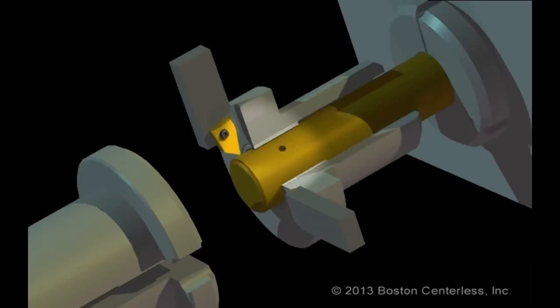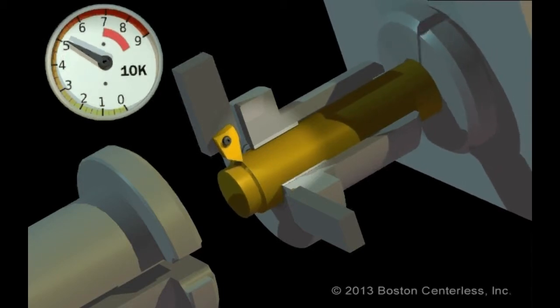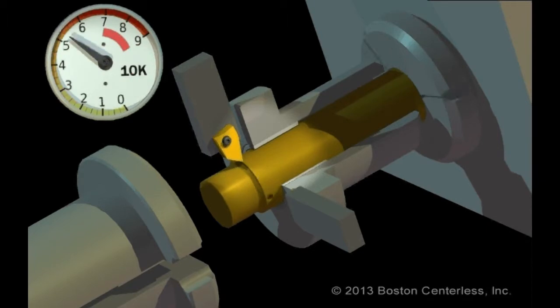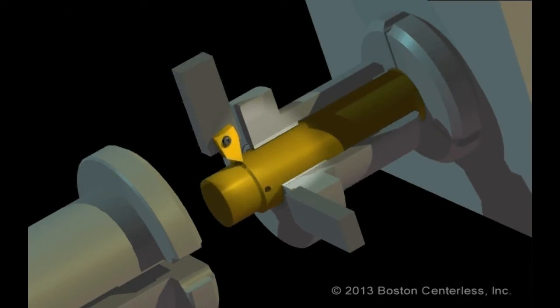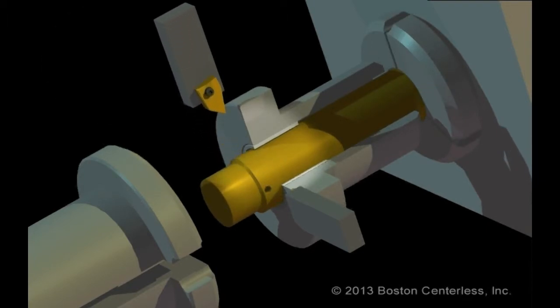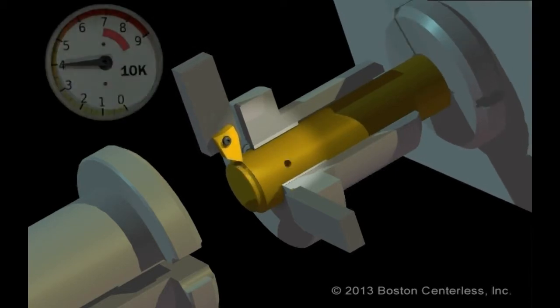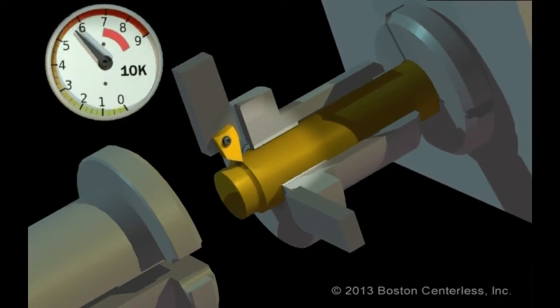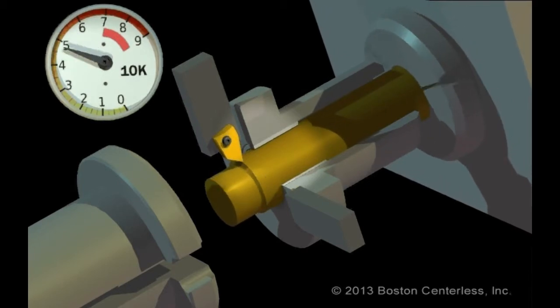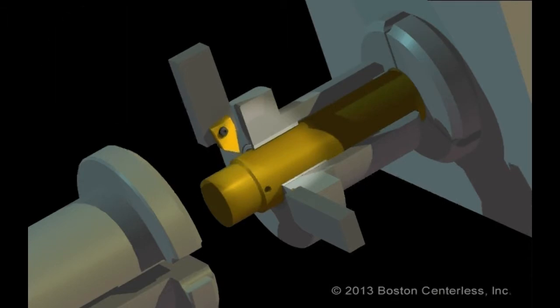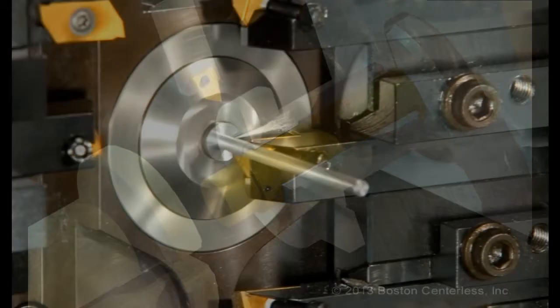The second example, similar to that of straightness, is the tool is always cutting varying amounts of material as the bar rotates, regardless of material speeds. When this happens, the tool stress is constantly changing, and any time you have changing stresses, tool life significantly suffers. In this case, the tool sees varying bending and contact stresses.